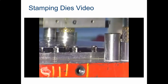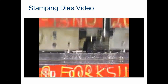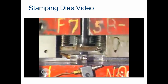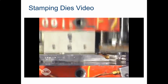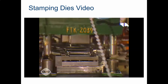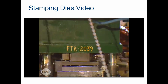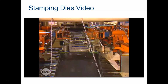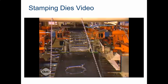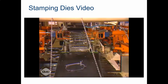In progressive die operations, parts are made from continuous coil stock and remain connected to the stock by a carrier strip during each successive operation until the final cutoff and discharge from the die. In transfer die operations, parts are blanked before or at the beginning of the sequential operations. Mechanical transfer devices grip and move the individual workpieces from die station to die station within a single die to complete a progression of operations.